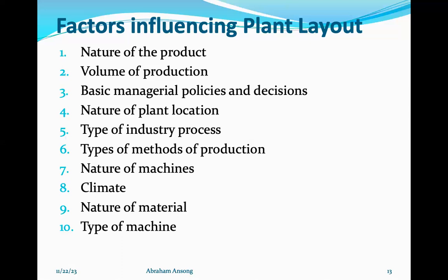Okay. The nature of machines. So the nature of machines and equipment also affects layout of plants. If machines are heavy in weight or create a noisy atmosphere, stationary layout may reasonably be adopted. Okay, heavy machines are generally fixed on the ground floor. Ample space should be provided for complicated machines to avoid accidents.